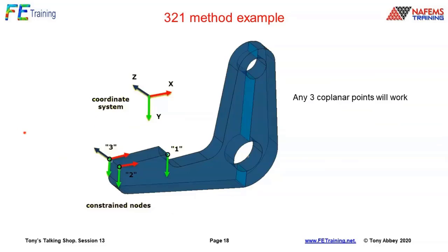So I also put my minimum constraint set on. Here I've chosen that particular face. I could have chosen that set, put a slicer anywhere to give me three coplanar points. We'll create nodes and do my 3, 2, 1 through them.